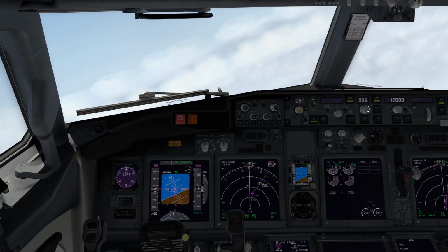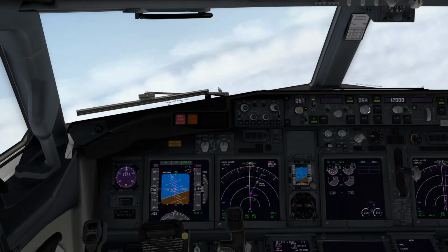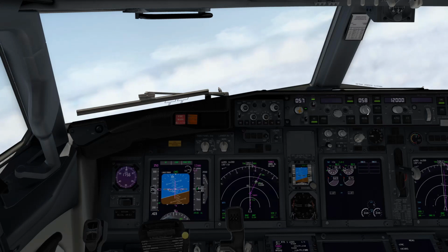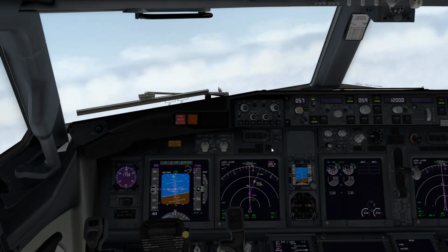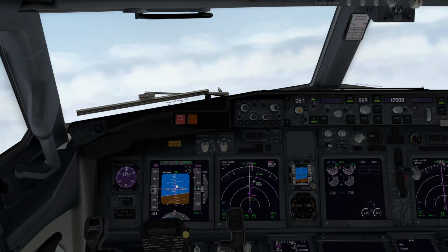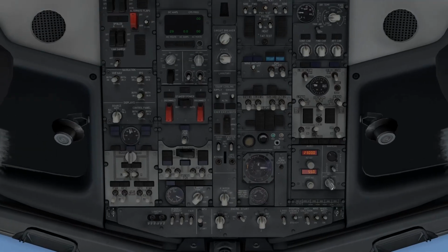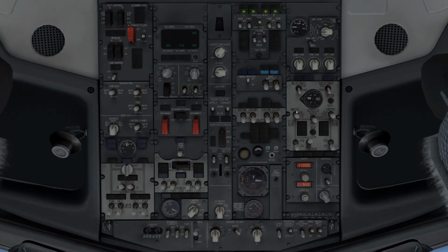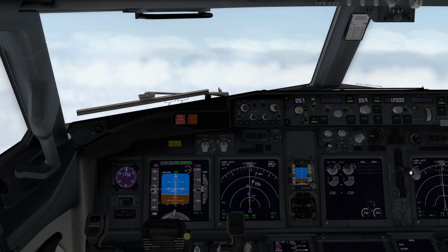And the one thing about this airplane is you want to keep the heading bug synced up, so you have to do that manually. Move the heading bug. And after takeoff checklist says engine bleeds on, or on Pax Auto. Landing gear, it's up and it's off.